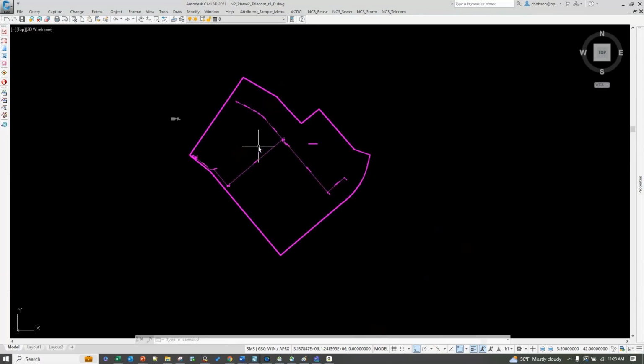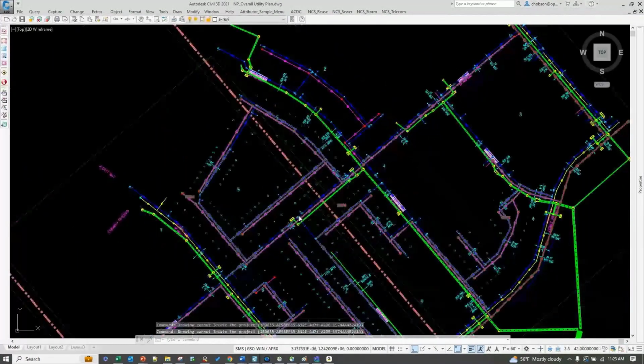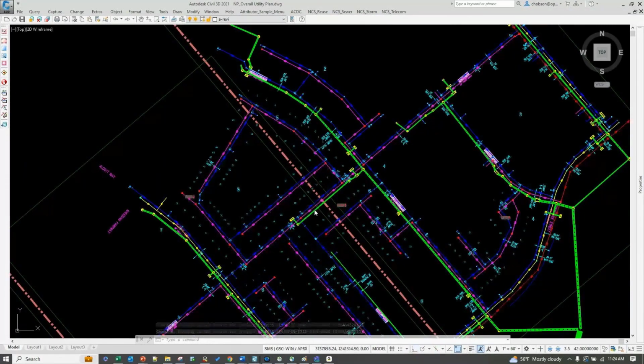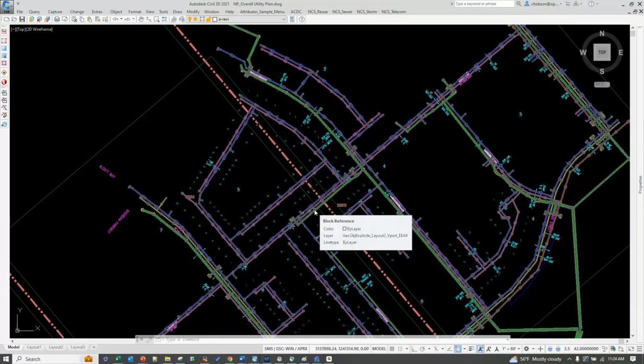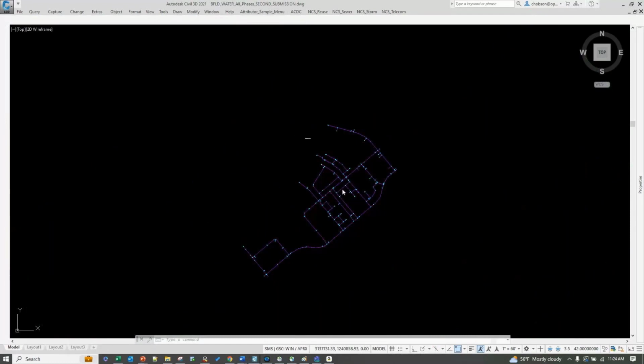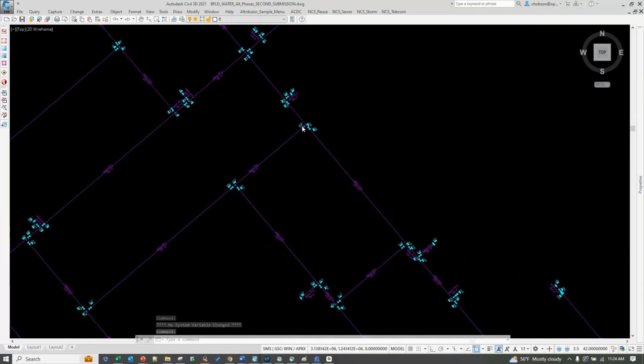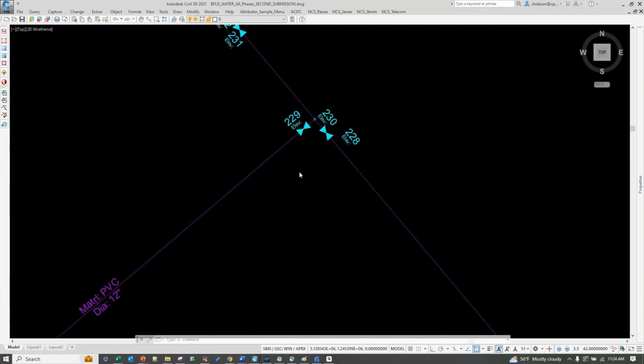And by the way, this here, if I just walk through it in this particular project, I showed you this. When they're drawn, normally what happens is the drawing set is a set of XREFs. We want in model space the actual asset. So we would split these either as the utilities being separated from the cadastral, or we'd have one drawing for each of the utilities. It doesn't really matter if the utilities are one of the same. Here in this particular setup, we've drawn the water. So if I go here, here's the actual water from that plan that you saw, but it's been drawn with ACDC standards, and I'll go in and actually draw some and show you.